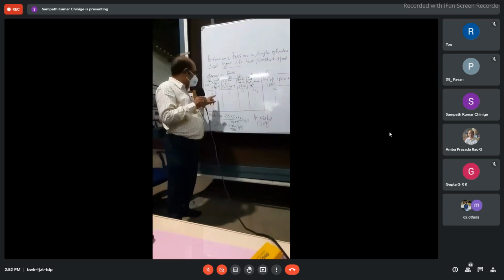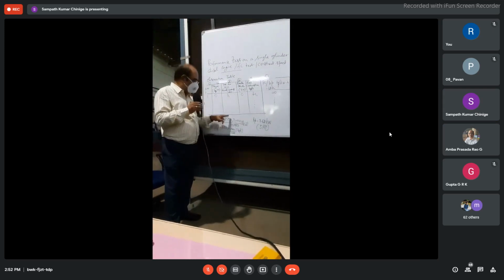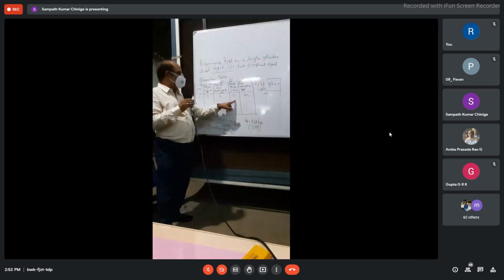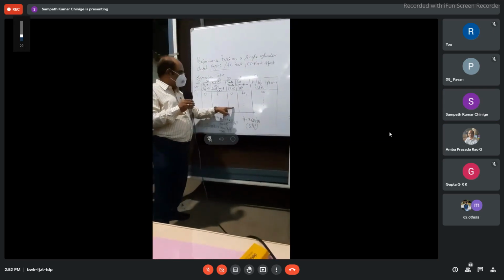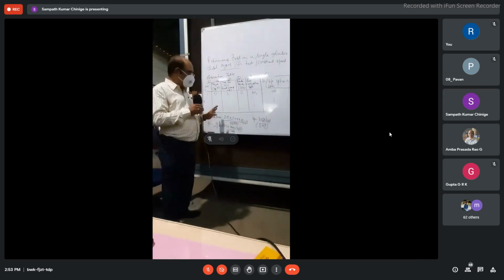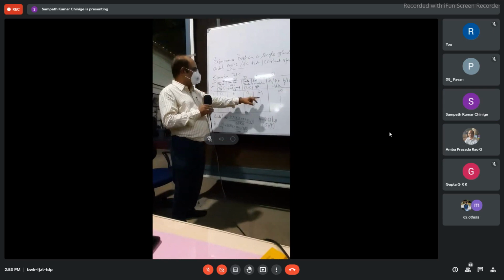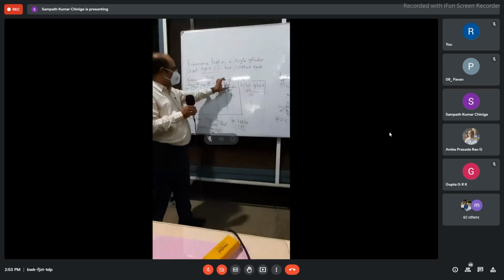So what is the 0.5? It is the next torque reading. Substitute that 0.5, calculate this value, and we get the value of BP1. Likewise, BP1, BP2, BP3, BP4, corresponding to the last torque meter readings. Similarly, we get FC1, FC2, FC3, FC4, FC5. So now, after this, how do you calculate the fuel consumption?